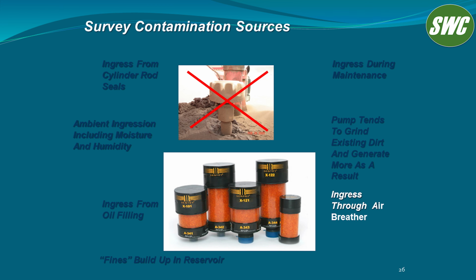Obvious but basic, you should clear all that dust off of the top of the reservoir around the filler breather, and you really need to use a quality desiccant breather.